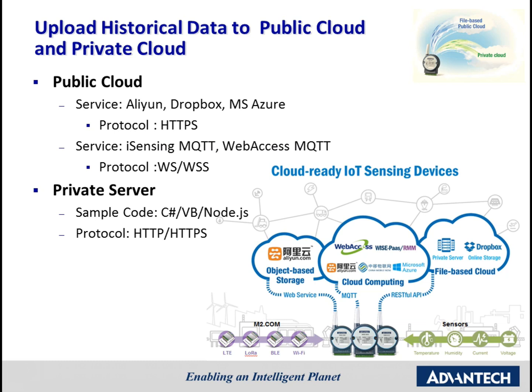All of these cloud servers transmit the data by HTTPS security protocol. For Modbus and for the MQTT protocol, WISE uses WebSocket with or without TLS/SSL security function.